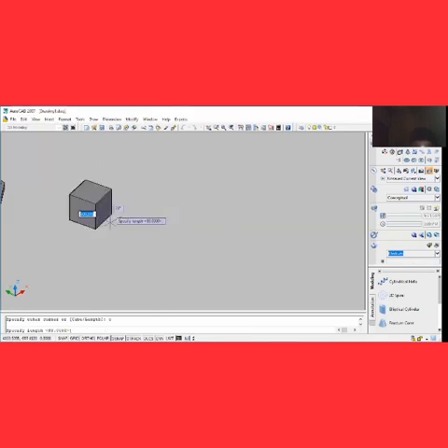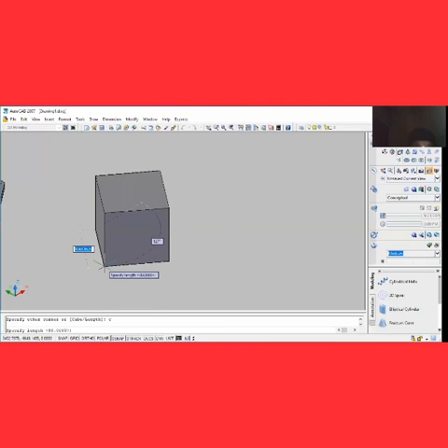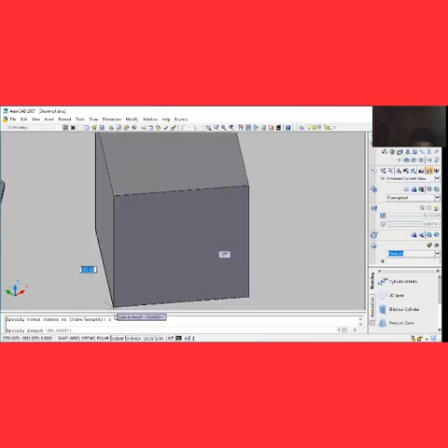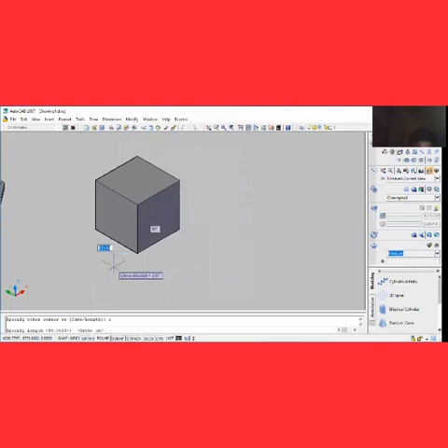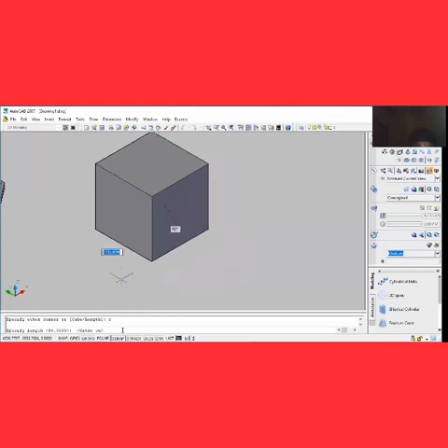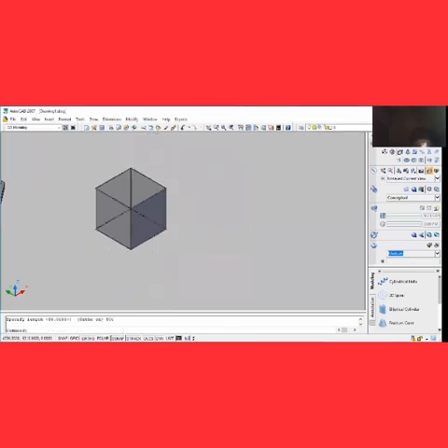So now it is telling you to specify the length of the cube. But it's always advisable to ensure your auto mode is on when using this command. So let's click auto. Now it is on. Good. Now this length we have to use, because it's asking us to specify a length, so we can choose a length of 800 mm and then enter. And this is your cube. Of course, your cube is length, breadth, height, having the same sides.